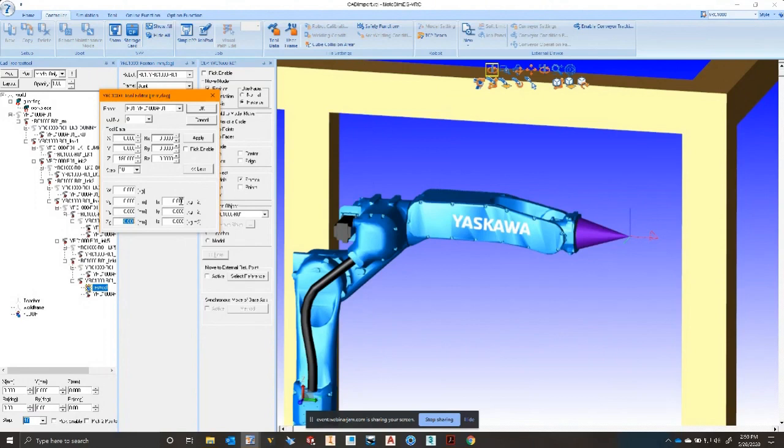Please do not leave these empty. When you fill in your tool data in the real controller, everybody, please fill out every single field. You can get this from your 3D CAD model. If you don't have a 3D CAD model, go weigh your tool, estimate your CG, and use the calculations provided in our controller manual to get your moments of inertia.